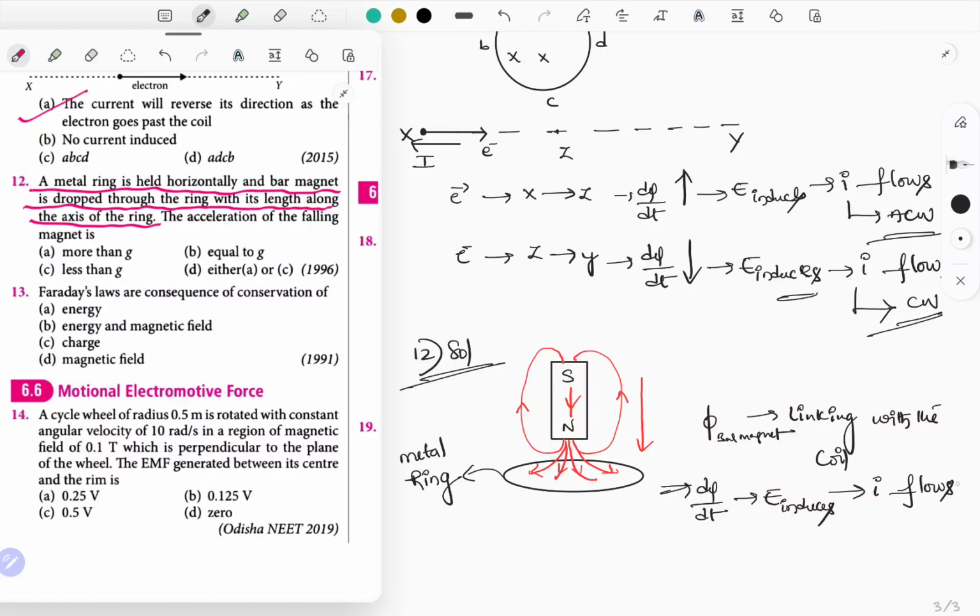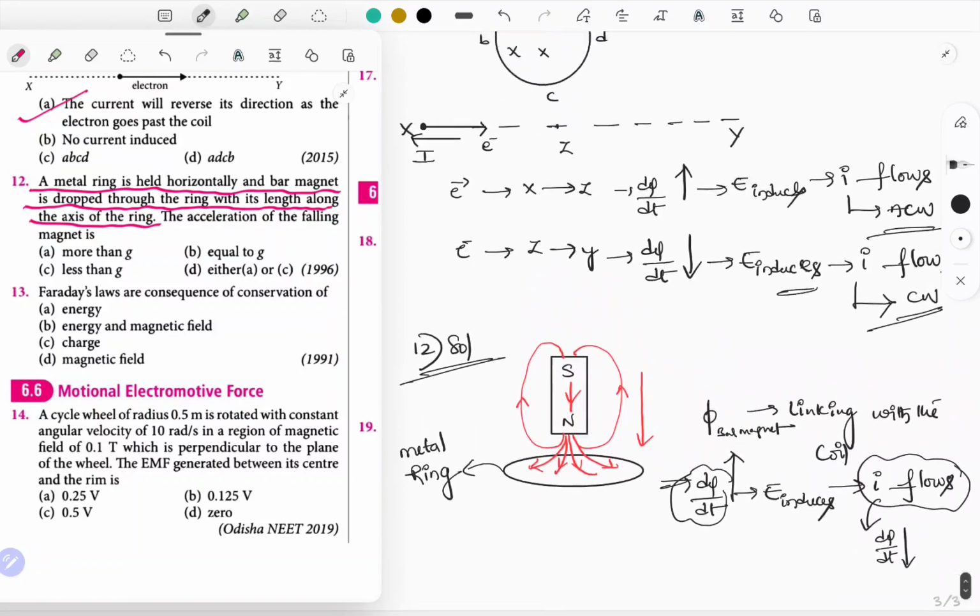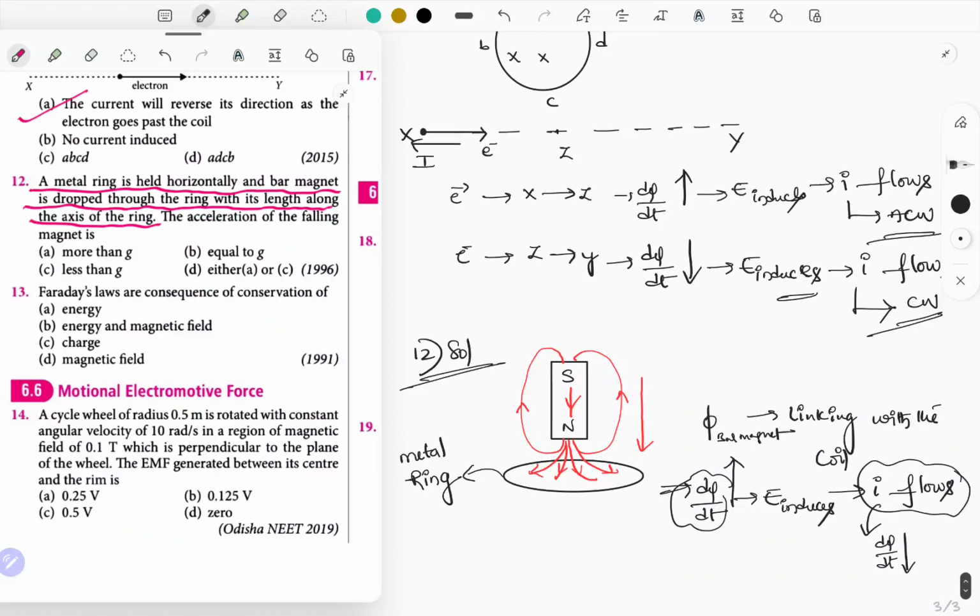How? So current is flowing in the coil, we have to decide the direction. How will the current flow? So that it opposes the change in flux linkages, right? In this case, are flux linkages increasing or decreasing? Increasing. Then what should I have to do? I have to decrease. To decrease flux linkages, in which direction should current flow? It should flow in the anti-clockwise direction. Here it is. This is how current should flow. So this is the induced current, which opposes the increase.